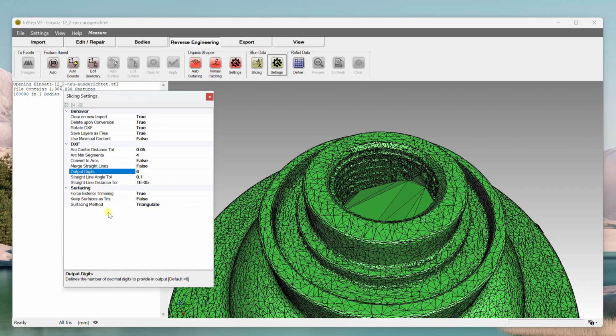Lastly, down here with the surfacing, this applies if you're trying to generate a surface plane as opposed to an intersection curve. And we'll cover that real brief. When we create an intersection curve, the export option will allow us to save those as an STP or a step file, in which case the plane is not being laid flat, it is being provided to a CAD application as just a planar surface. For those cases, we do want to use exterior trimming. That doesn't actually apply to all the algorithms, but we generally want to keep that on.